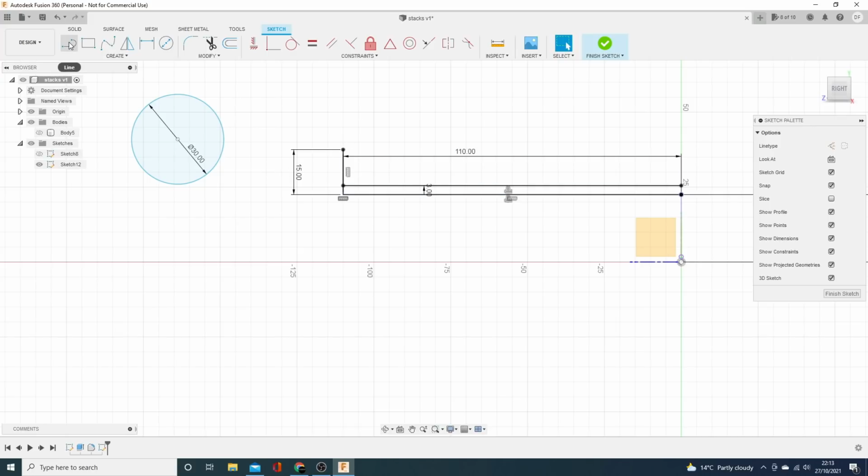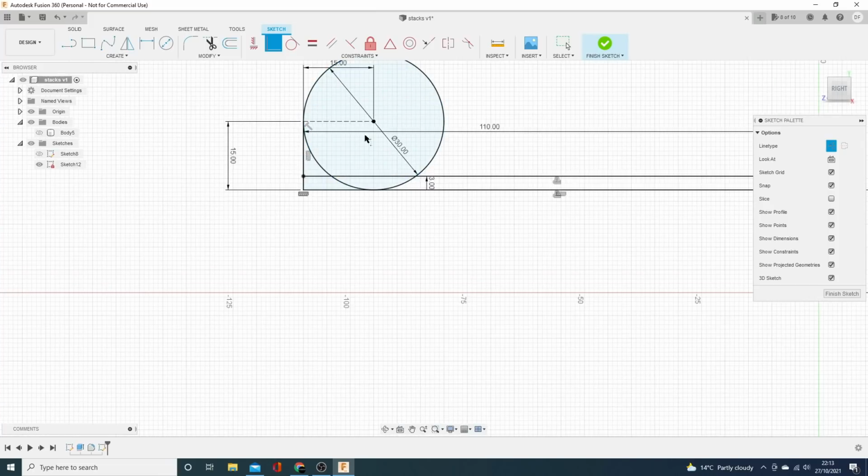So what we need to do is bring that in to the right position. I think if we create a construction line coming off here, 15mm, again, because it's coming off constraints, we know where it is, and then we can simply put this constraint to there, and now we have a nice continuous line that we can pick up that goes out to our point there.